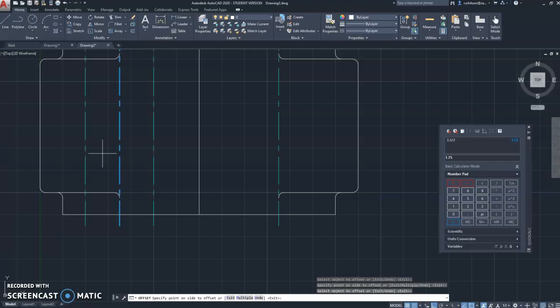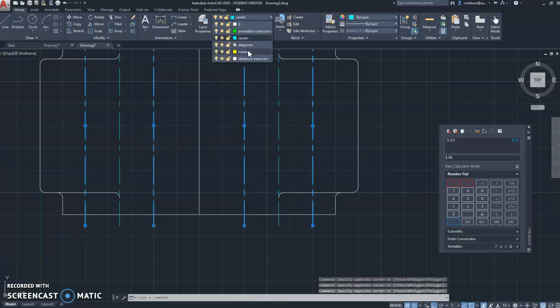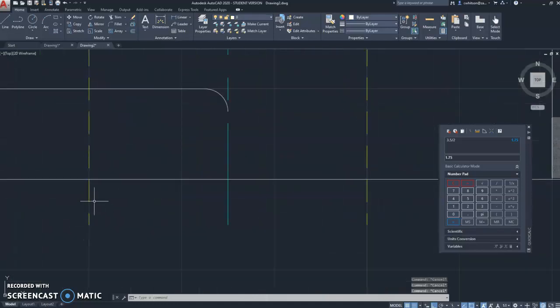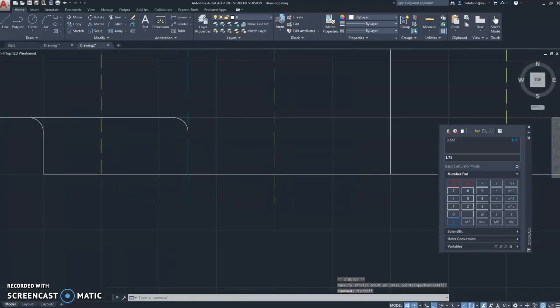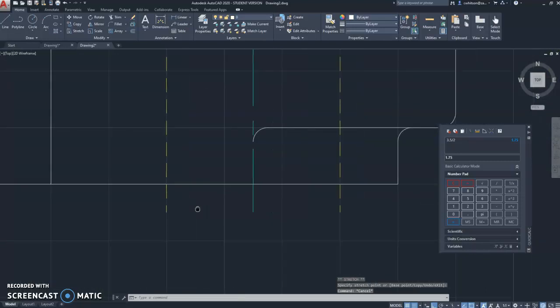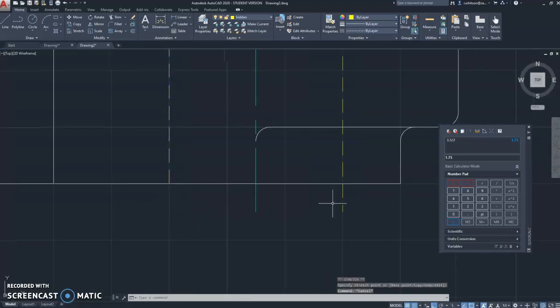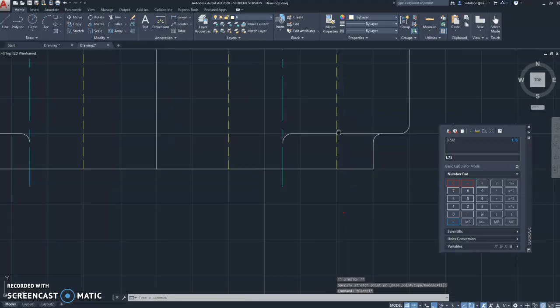I'll offset this to the right and the left, and the right and the left, and then these lines become hidden lines. Not center, they're hidden. And sometimes I see students leave hidden lines extending out beyond the edge of the part, just like a center line, and that should not be the case. The hidden lines are actually representing a real physical, tangible characteristic of the part, and they have a specific termination point. They're not like center lines that are just imaginary.